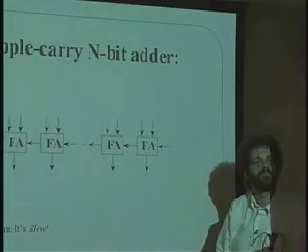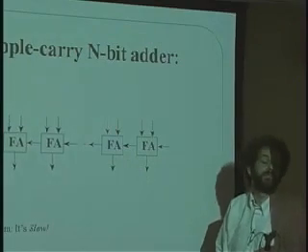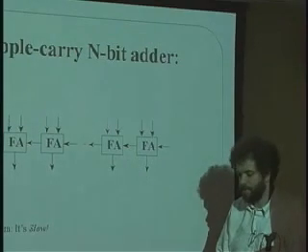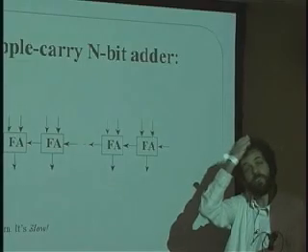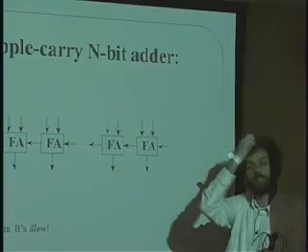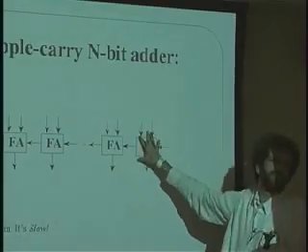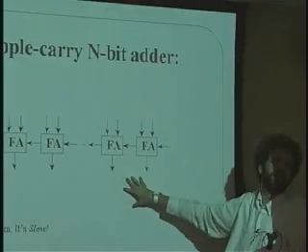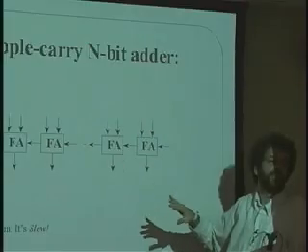But wouldn't you have to check all the way along the line anyway, in case there were, say, 2 1s in the n-1 position? Sure. Absolutely. There could be a whole bunch of zeros on both ends and 1s in the middle. So then the question is how do you know when you're done, right? And of course, the safe thing to do is you wait for 32 times however long it takes one of these guys to work, and then you know that you're done. Or maybe you build some extravagant circuit to find out when you're done.